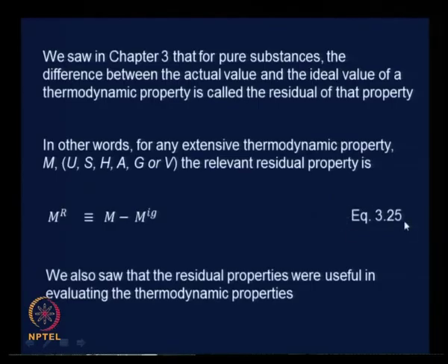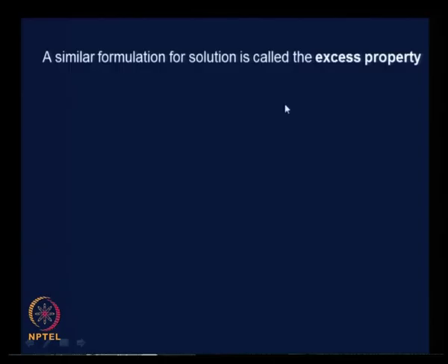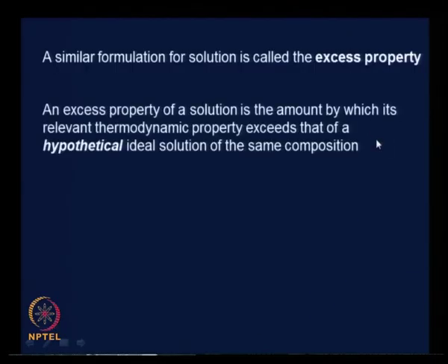This was equation 3.25 that we saw earlier, and we had used the residual properties extensively to estimate the various thermodynamic properties, and that is the utility of these residual properties. It is a very simple definition, but it comes in handy because the data is easily available in terms of residual properties. A similar formulation for solutions, that was for the pure substance, this is for the solutions or mixtures, is called excess property.